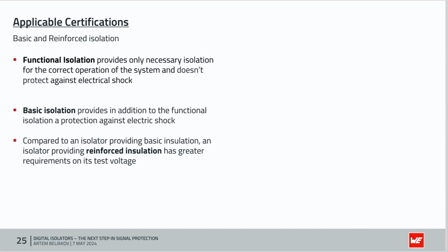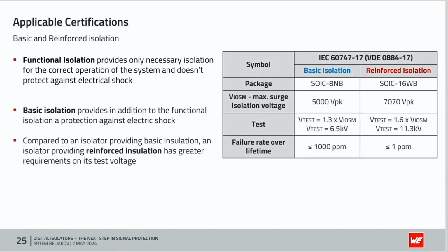But what do greater requirements mean? You can see on this table. As I already said, our digital isolators in the SOIC 8 narrow-body package provide basic isolation, and products in the SOIC 16 widebody provide reinforced isolation.